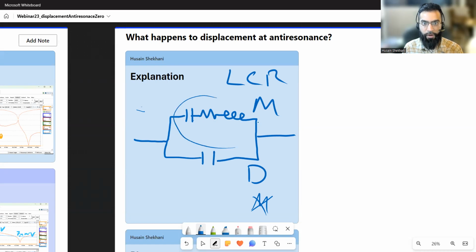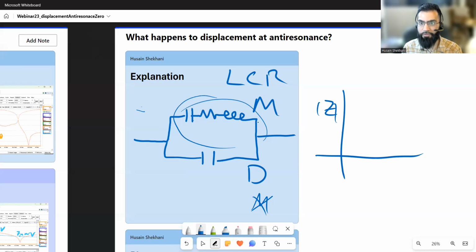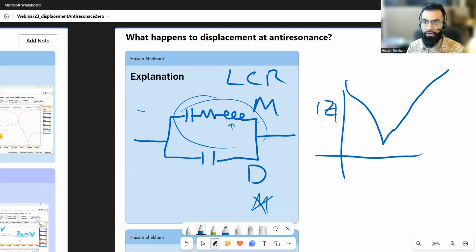So this part here is responsible, if you're thinking about impedance, for this dip. And if you only had this LCR, you would actually go back up. So this actually approaches infinity. And as you go to infinite frequency, this inductor takes over, or basically the inertia takes over. The inertia is so much you cannot even move the thing. There's no current generated.